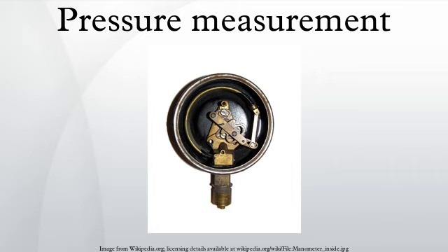Thermionic emission generates electrons, which collide with gas atoms and generate positive ions. The ions are attracted to a suitably biased electrode known as the collector. The current in the collector is proportional to the rate of ionization, which is a function of the pressure in the system. Hence, measuring the collector current gives the gas pressure. There are several subtypes of ionization gauge.